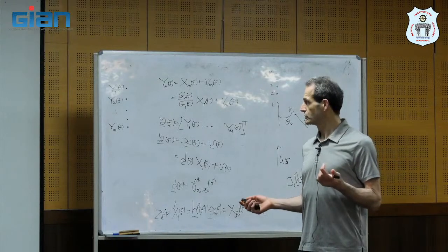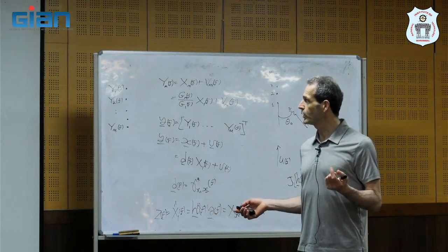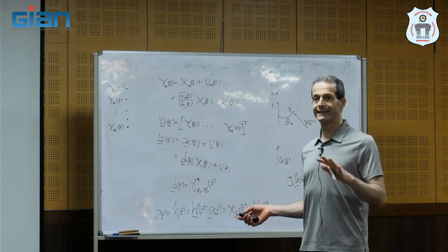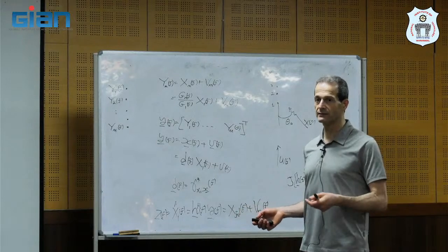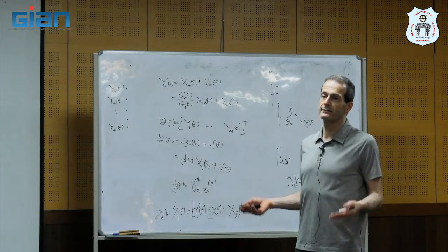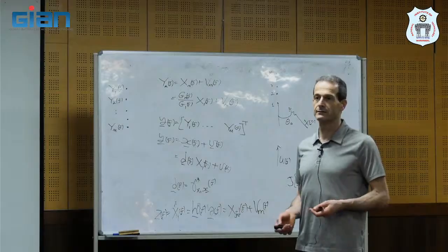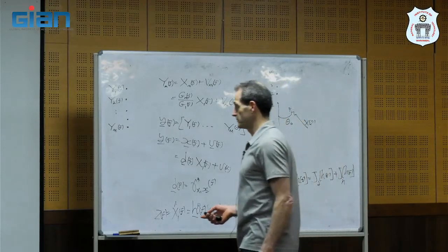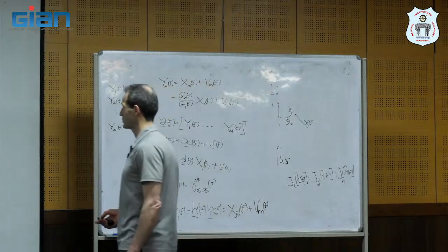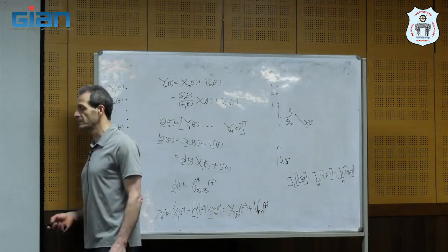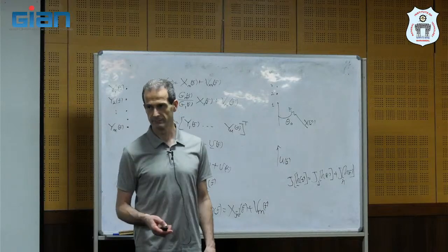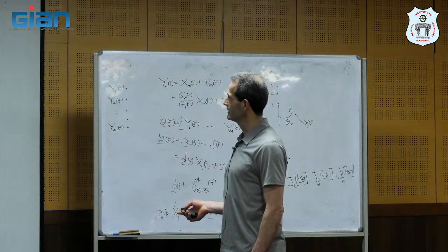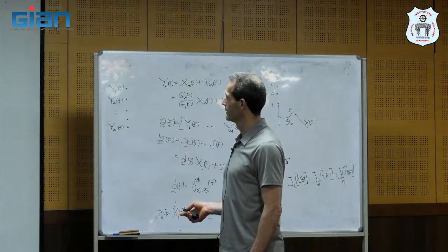Remember, the broadband MSE is the summation of the narrowband MSE. So if it's a summation, and we optimize each filter for each frequency independently for different frequencies, necessarily we get the minimal broadband MSE. Okay? So the narrowband filter optimizes not only the narrowband MSE, but also minimizes the broadband MSE.